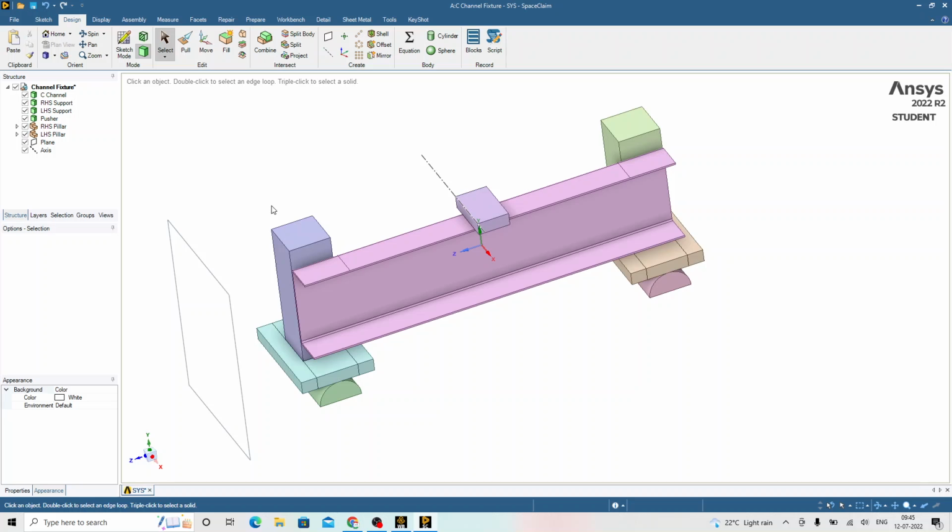Escape command can be used to come out of all the commands. We click on one vertex, press and hold control for another vertex, click on the datum axis. So a datum axis can be created by using 2 points as well. Commands like linear pattern, circular pattern and group pattern also can be used when we are dealing with